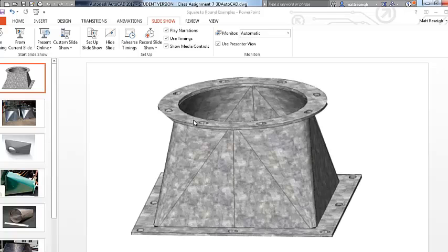And there's other ways too. Sometimes there's a transitional piece between the squared around before I flange it. So I like this one shows a real simple version, which is what we'll start with. A couple things to notice here. This is kind of a concentric, or what I'll label as an equal taper squared around, meaning that the center of the round is directly over the center of the square. So all sides kind of taper equally. So all these sides around this thing are really symmetrical, and it's definitely the easiest type of these we can look at.